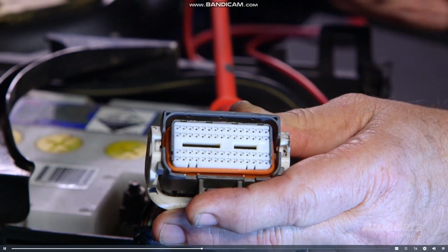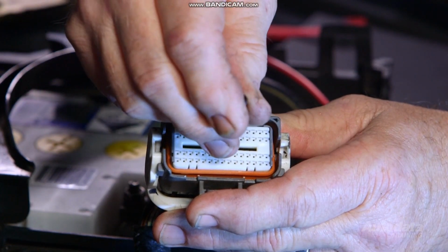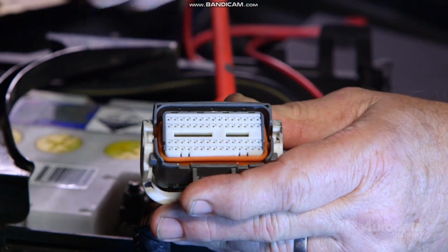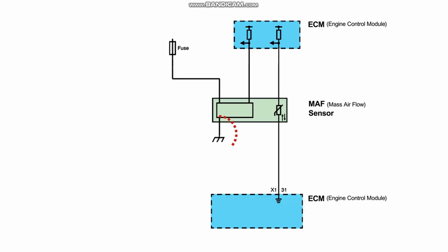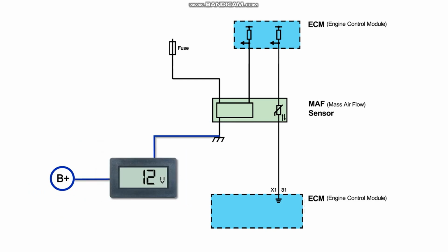Check any connectors in the circuit for corrosion and the correct terminal tension. If the circuit goes to a vehicle ground, then test this point to battery positive. If the reading is now correct, then the resistance will be between the ground point and the sensor connector. Otherwise, it will be the ground connection itself.